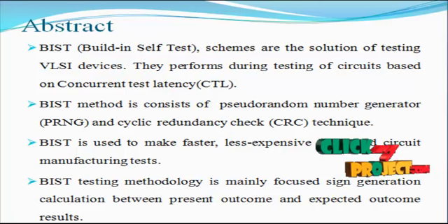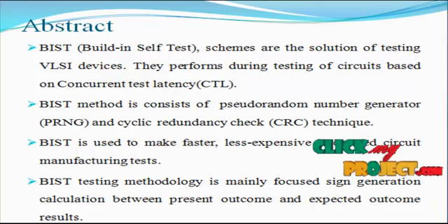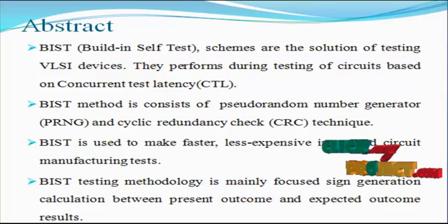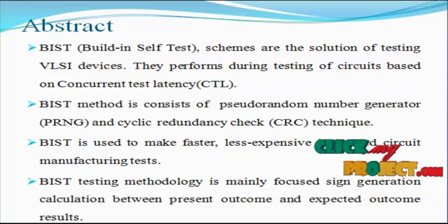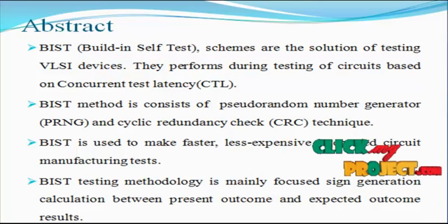It is compared with linear finite state machines, a linear feedback shift register and a ring generator driving an appropriate phase shifter, and it comes with a number of features allowing this device to produce binary sequences with pre-selected toggling activity. We introduce a method to automatically select several controls of the generator, offering easy and precise tuning. The same technique is subsequently employed to deterministically guide the generator towards a test sequence with improved fault coverage.